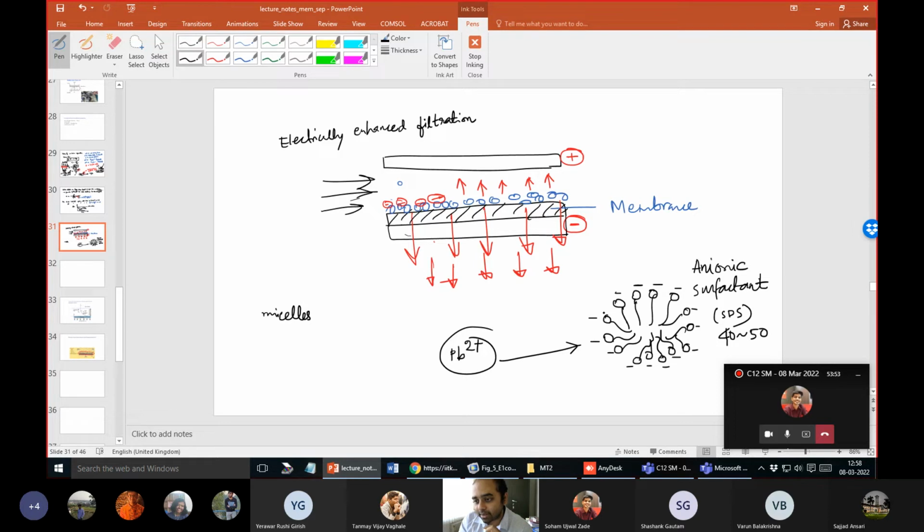So to remove this lead micelle complex, you can use a more open membrane. Let us say I can operate even with a microfiltration membrane. If I use a microfiltration grade membrane to separate this lead micelle complex, I will essentially be separating lead. That's my target. Surfactants are very cheap in the solution. The surfactant micelles are very large, so even with microfiltration, or ultrafiltration, you can remove these micelles. So the entire lead micelle complex will be removed.